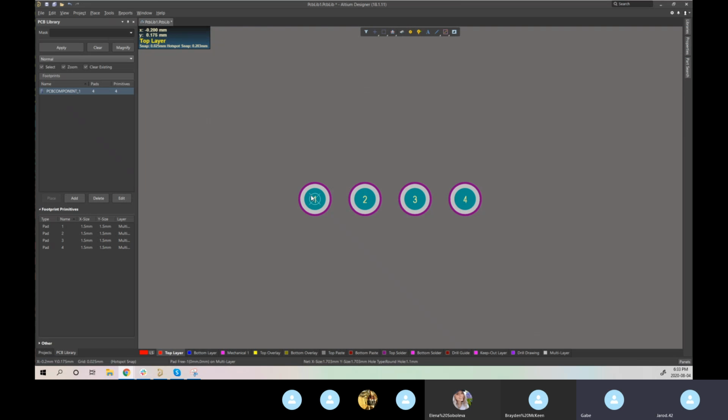It's easier for them to just manufacture a straight hole instead of trying to do a nice cutout. So whenever you come across components like that, it's best just to find the minimal sized hole that would allow for your design, and then use that.